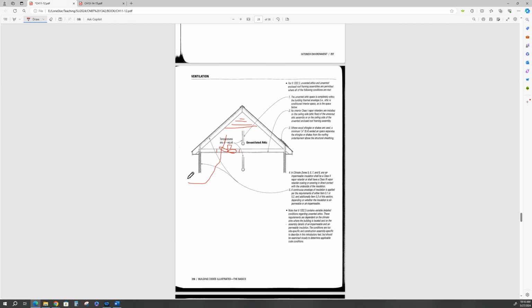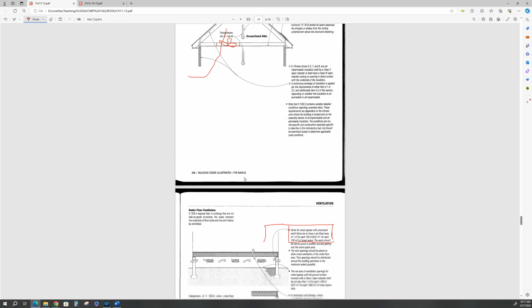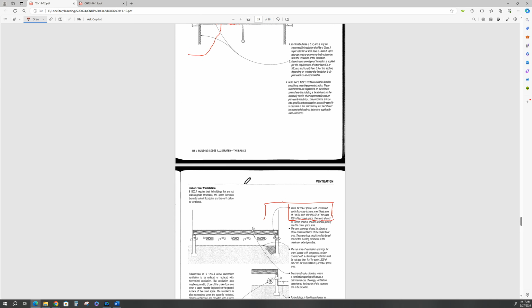Let's say you got a nice spring norther come in, and it's 68 degrees out here, and it's 80 in the house. Well, open the windows, turn on the attic fan, and in about 10 minutes, the entire house will have fresh air in it, and it will be the same temperature as the outside. And then close the windows and turn your AC back on, or leave it running. Whole house ventilation. I'm a big proponent for that.